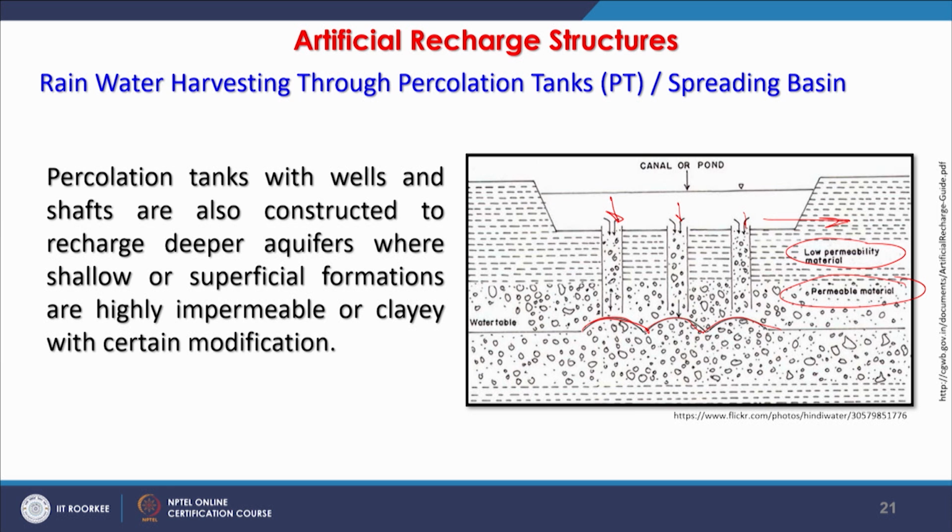A simple tank may not be as effective as having at the bottom of the tank a few wells, a few bore wells without any pump or anything, just left there to recharge the groundwater regime. So, these are also very good, especially in those areas where you do not have much weathering or fracturing at the top surface, but you know at a certain depth, after geophysical investigations, that we have confined aquifer conditions.